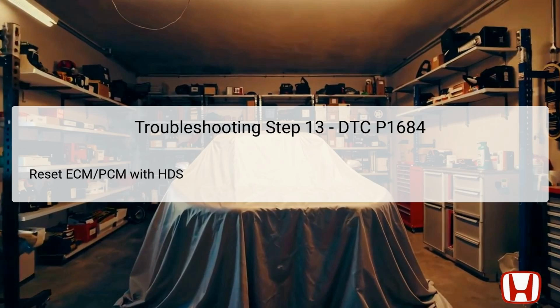The final step in troubleshooting DTC P1684 after installing a new throttle body is to reset the engine control module, ECM, or powertrain control module, PCM, using the Honda Diagnostic System, HDS. This reset clears any stored DTCs and allows the system to recalibrate and adapt to the new component. The ECM/PCM is crucial as it controls various aspects of engine performance, and resetting it ensures that the new throttle body operates within the updated parameters. This process is essential to confirm that the replaced component is now functioning correctly.